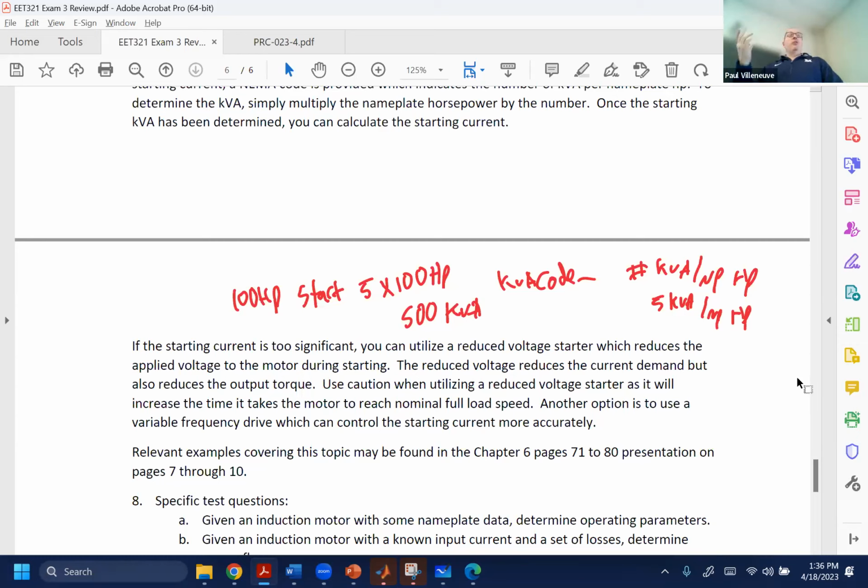And then they literally pull a vacuum, so all that resin gets sucked into the windings. If you just pour it on there, it doesn't easily get through, but when you pull a vacuum, it forces it through the windings. And then they gradually let it cool. Now you have a really solid insulation on these wires that can handle high temperatures, and the wires don't move. They're locked in position. So it's a hybrid oven and vacuum impregnation of the resin mixture. It's all done in one step.